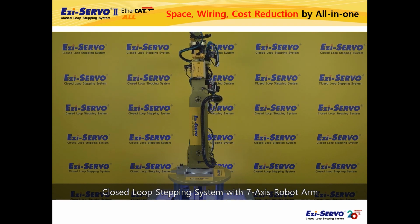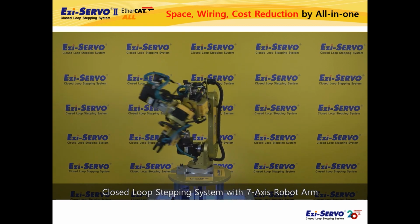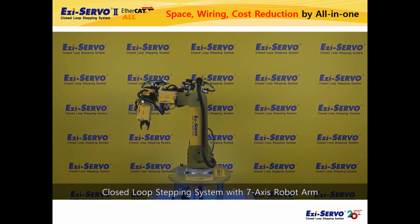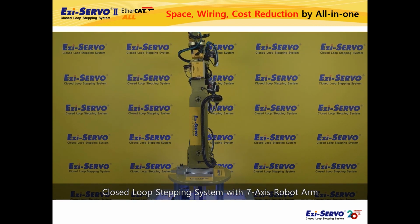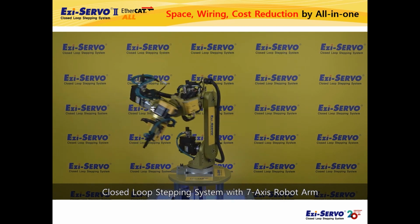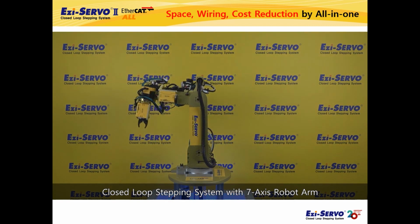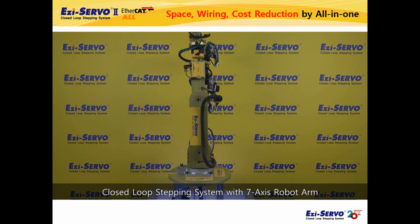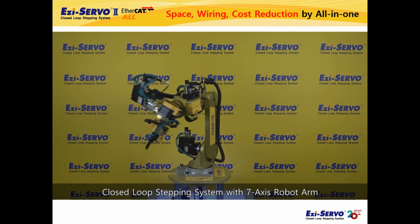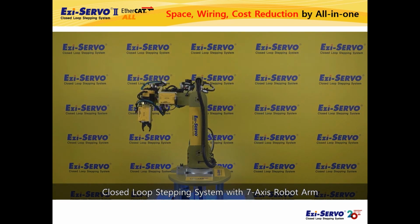Therefore, when all-in-one motor drives and mini drives are used, a separate control box is not required, and only one EtherCAT network cable from the EtherCAT master and 24-volt power cables are actually wired. In conclusion, since the cable wiring is reduced, there is a great effect of reducing the cost and preventing malfunction due to wiring. For reference, recently, the size of smartphone-related machines is small and the number of motors used is large, so wiring and space are becoming more important.